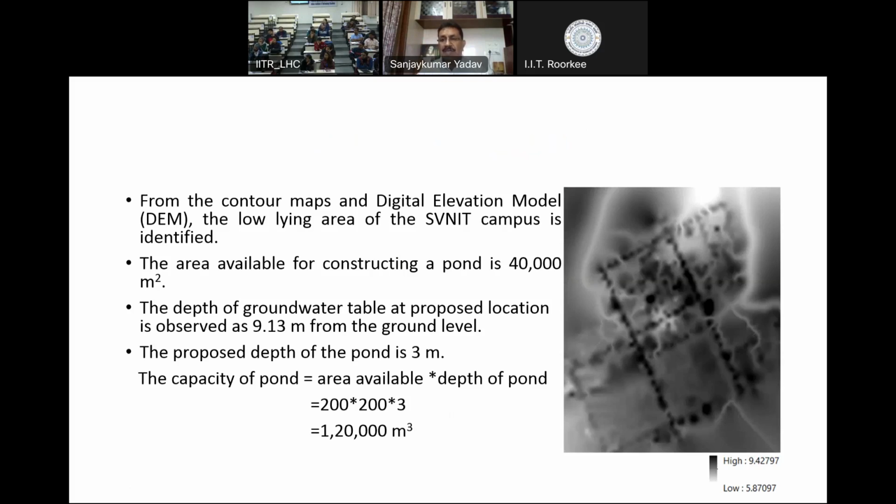I asked him, "Please share the borehole details, that is, the geological investigation carried out in your campus." Initially he refused, saying they did not have any geological investigations. Then I said, "Sir, yours is a new IIT. I am very sure that before constructing buildings, someone has gone for a geological investigation." And he sent me those investigations, and I found that at just 30 centimeters, that is approximately 1 to 2 feet depth, there was a hard rock.